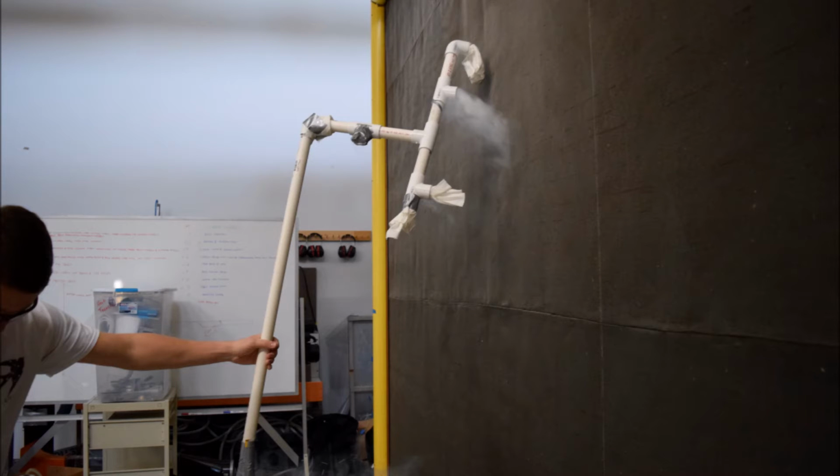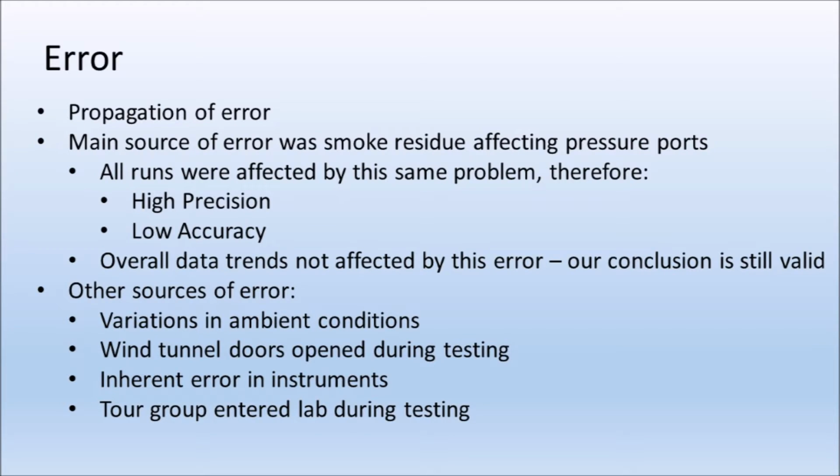One of the main sources of error we encountered during experimentation is tainted measurements from our pressure ports due to the smoke machine. Injecting smoke into the flow is a great way to visualize the effect the cylinder has on the free stream for vortex shedding and the wake as a whole. Unfortunately, a number of experiments were run before us using the same rigging as ours. This means the pressure ports positioned around the cylinder's circumference were exposed to an excessive amount of smoke beforehand. Therefore, within the pitot tubes, there is a significant amount of residue that will influence the pressure being measured and recorded by the scanning valve.